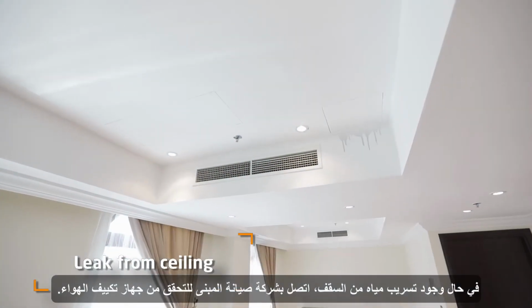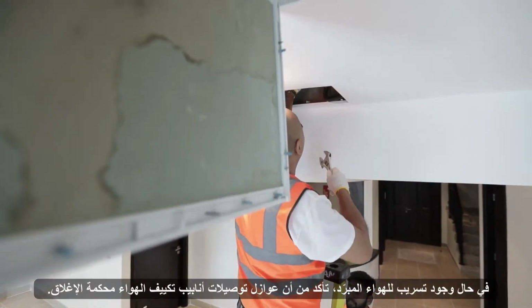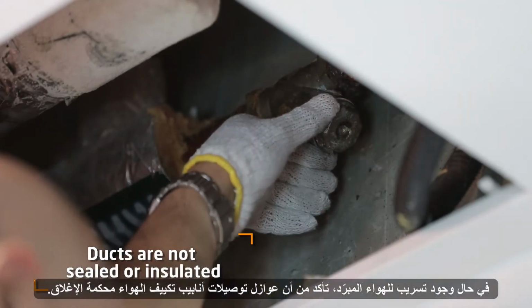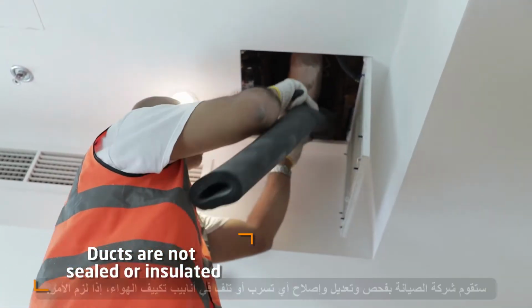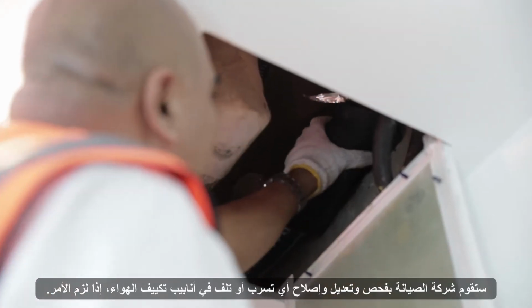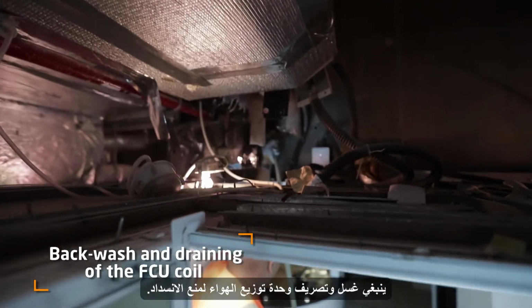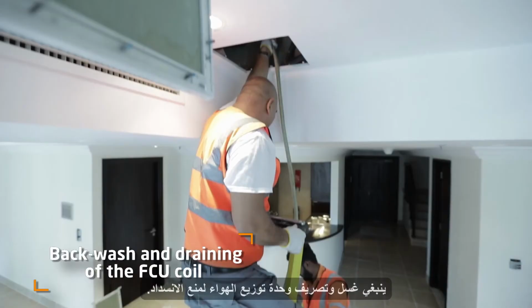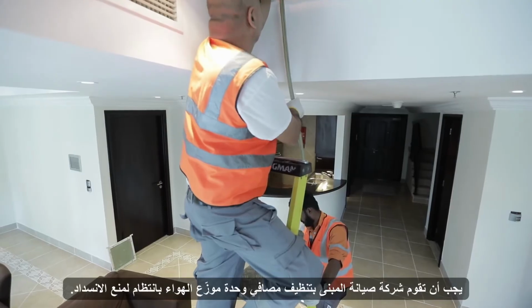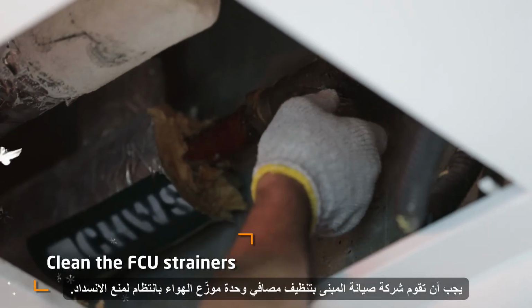Should you notice a leak from your ceiling, contact your building's maintenance company to check your AC. You could be losing cooled air to the outside if the ducts are not sealed or insulated correctly. The maintenance company will check, adjust and repair any leaks or damages to the AC pipes if required. Backwash and draining of the FCU coil are required to prevent clogging. Also, your building's maintenance should clean the FCU strainers regularly to prevent clogging.